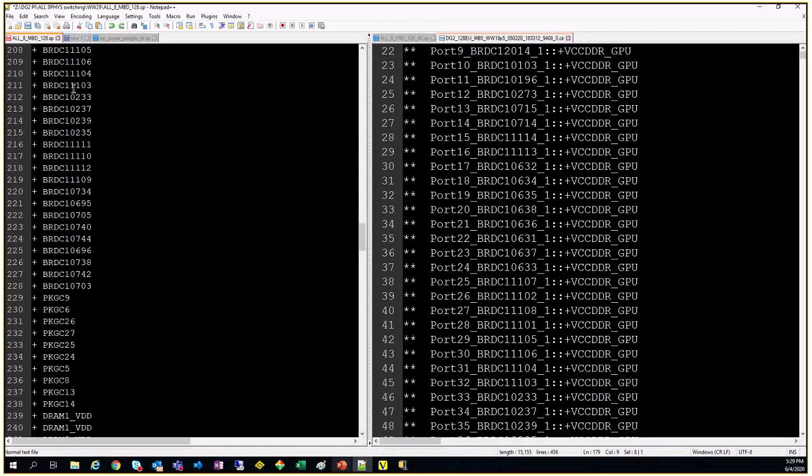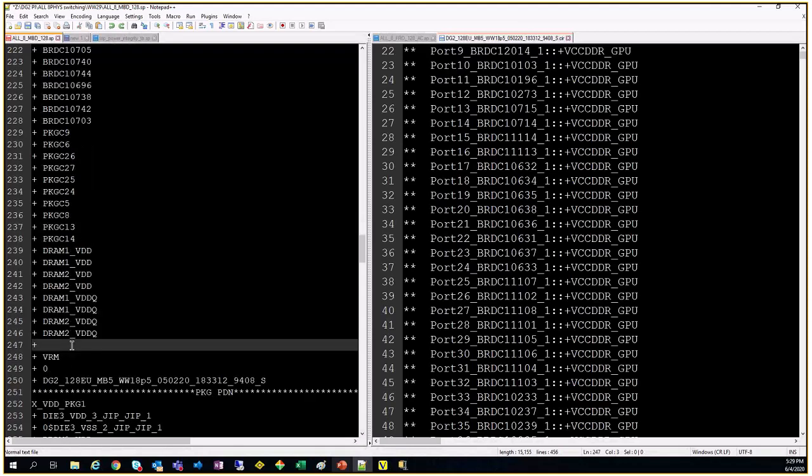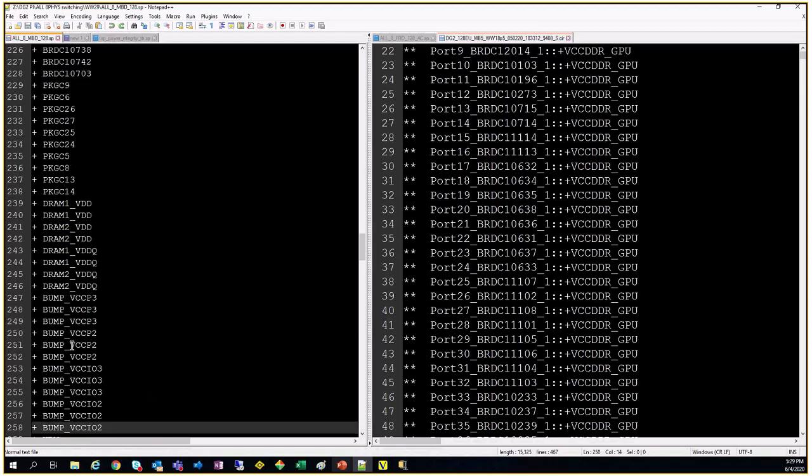Then there is one extra feature you have to add, which is this 0, a reference port. This is specifically done for .cir files or S parameters, wherein your port is taken reference as ground when extracting. So for the purpose of the calculation, you need to add this 0 over here. You're telling all my ports are referenced to 0 potential ground. And then you have your subcircuit name, which I'm calling over here. So where do we get the subcircuit name from?